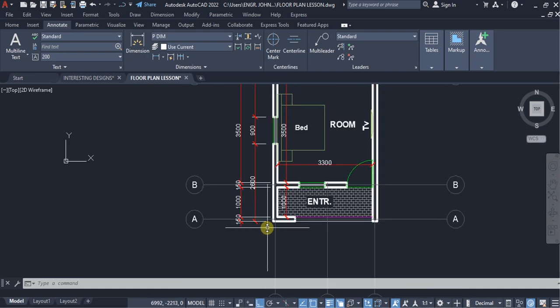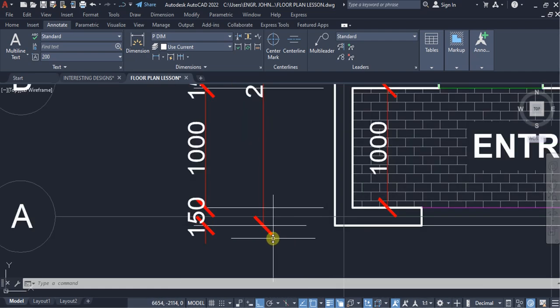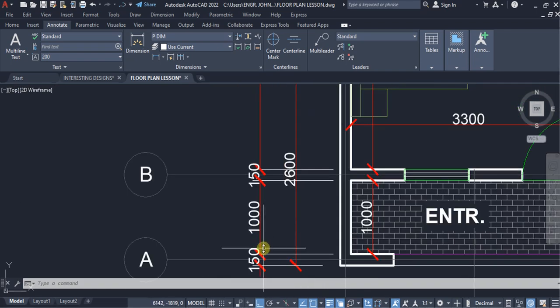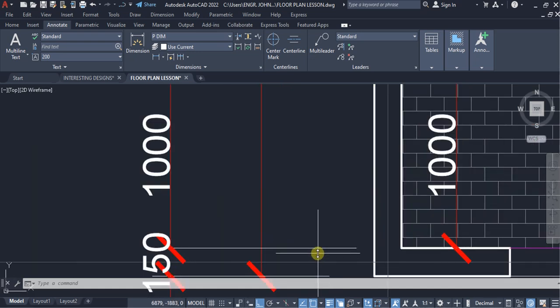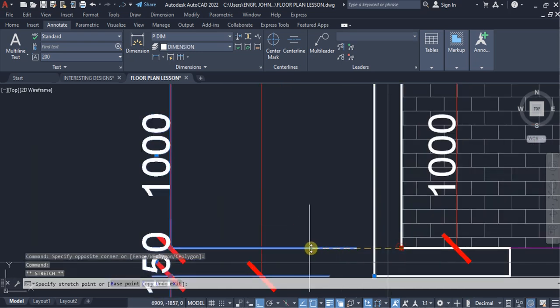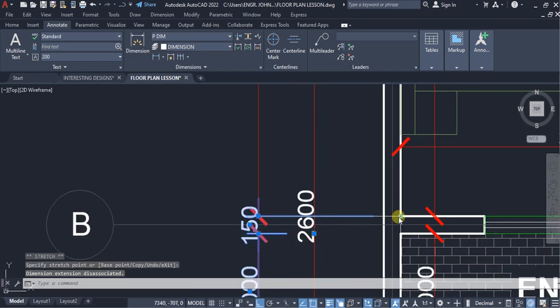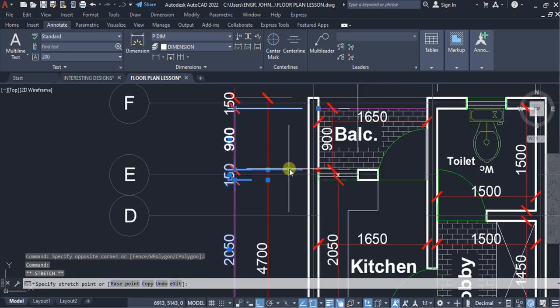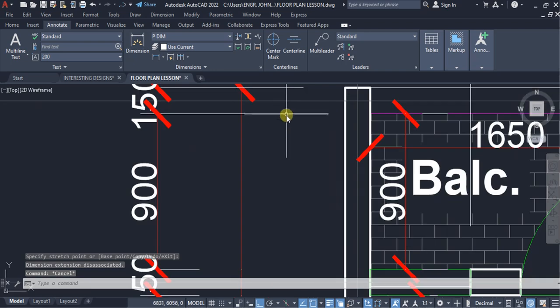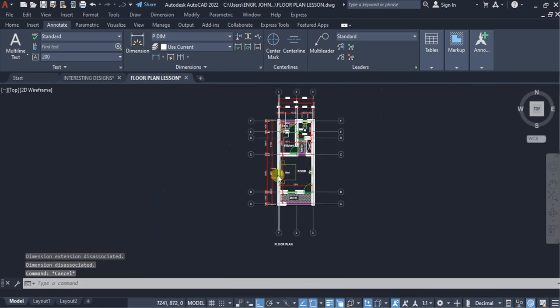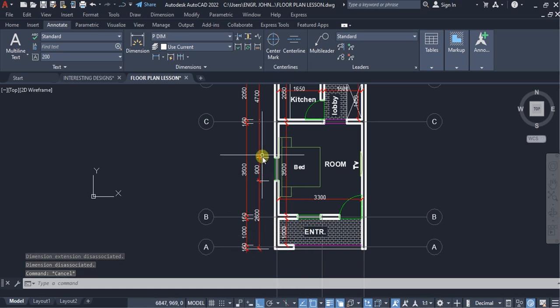Then again, for best practice, when you're making dimensions, as far as these architectural thick lines are, you will notice that the next dimension line will just cut across this line without architectural thick. What you just have to do is to select it, and you can pull it from that point to this point. And you have it so that they will all stand on their own.